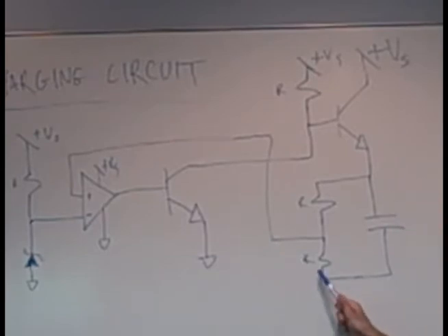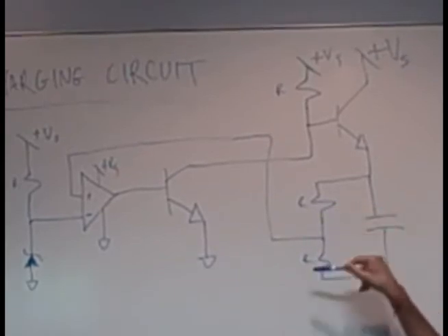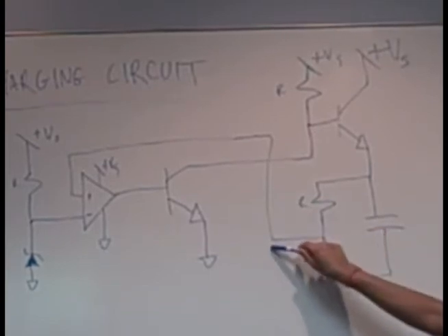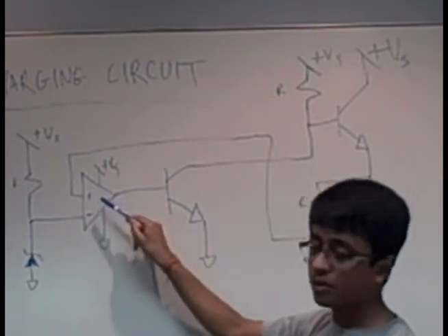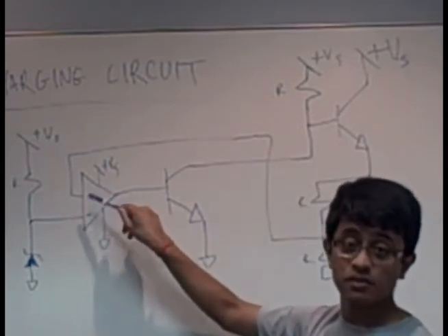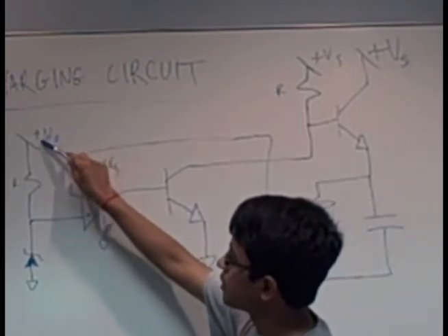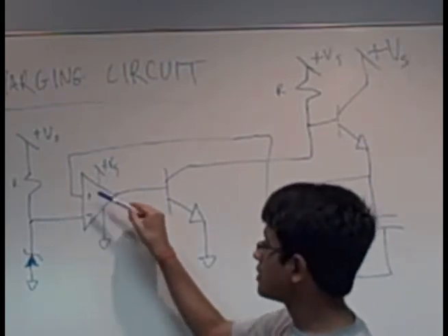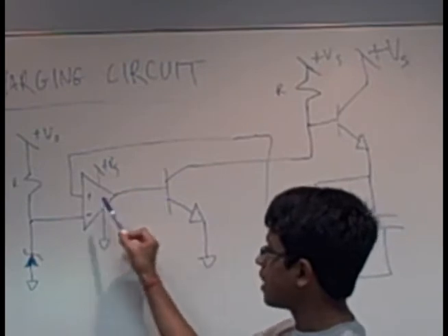Once it goes through, it meets the voltage divider, which is done by two identical resistors. Once it's halved, it feeds in through this wire, which goes all the way to this op-amp over here, and that value is the plus input for the op-amp. And as you can see, we have the other part, where it comes through a plus VS, a resistor, and a Zener diode. Once this value reaches 2.5, it allows flow through this op-amp.